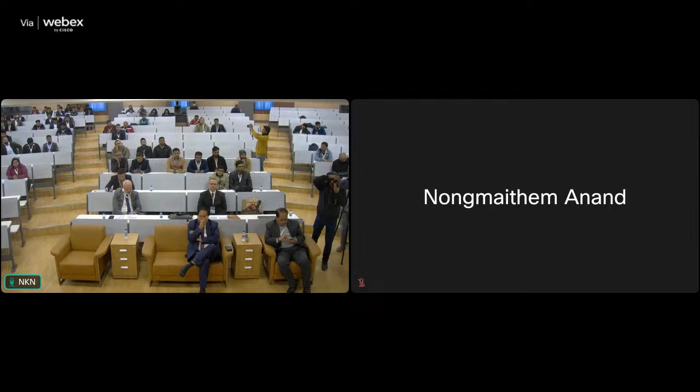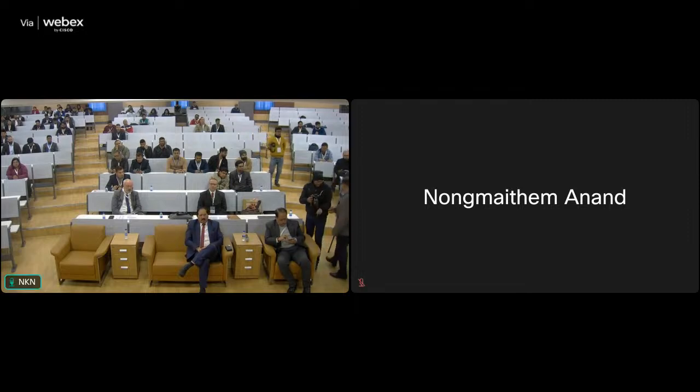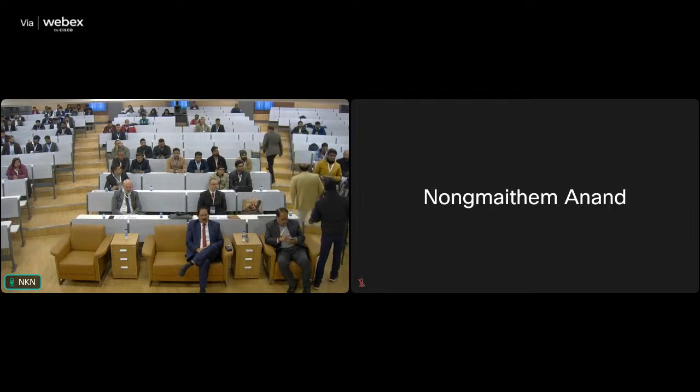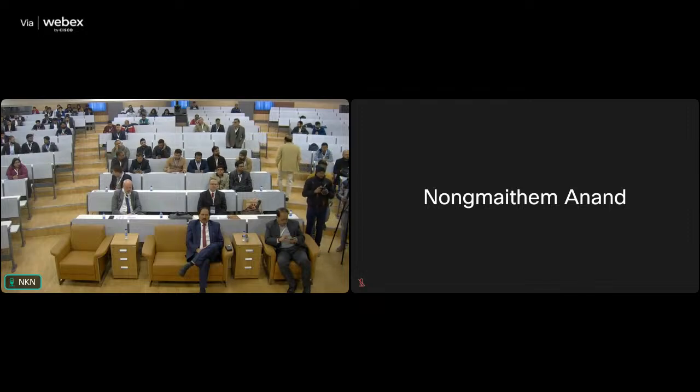Now it is understood that, like the pre-grouting, the full column grouted untensioned rock bolts, I have mentioned untensioned rock bolts here because this will act really as the active support when it is grouted. Rock bolts shall also help in improving the rock mass quality. So this has been emphasized by Sun et al. in 2012.